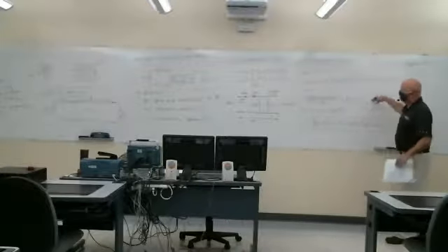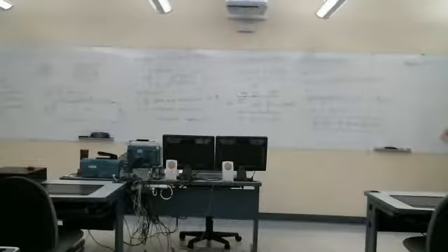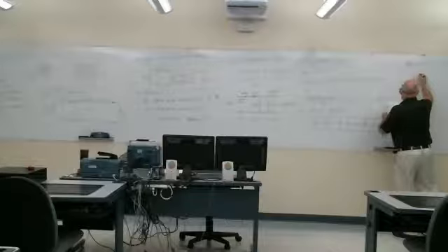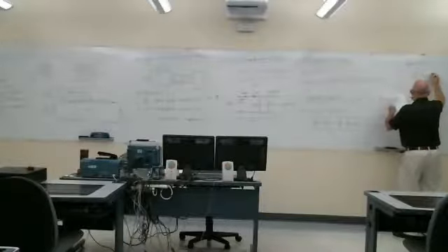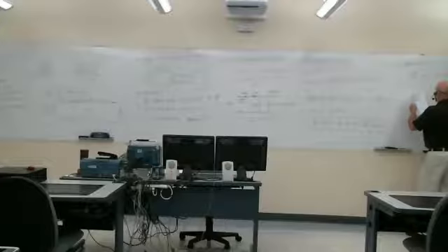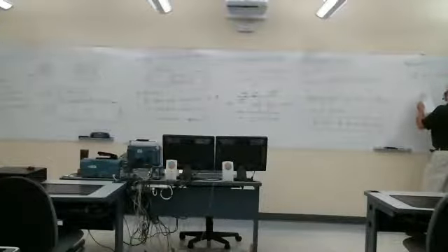I go through the same set of steps, and I get another differential equation. I'm going to skip the derivation. I(z,t) is equal to G prime V(z,t) plus C prime partial with respect to t of V(z,t).